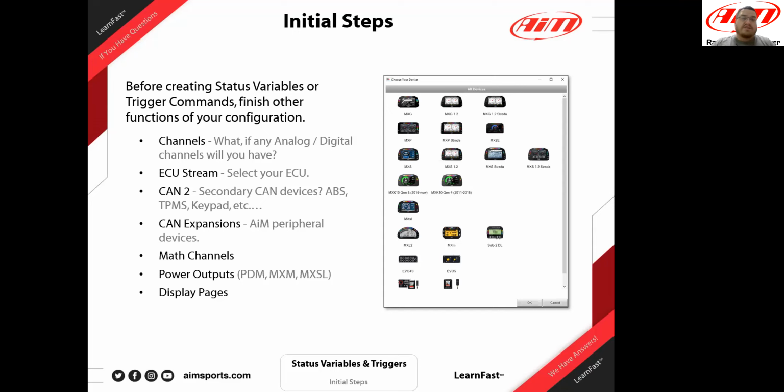So first, you'll need to set up your channels. Very simply, what are you getting for analog and digital channels? If you're plugging things up, go ahead and program them. You might grow, you might add things as you go, but consider this a starting point. ECU streams, easy enough. If you're using one, go ahead and select it. CAN 2, this one's tying in more and more. We see growing CAN 2 usage, and with the PDMs especially, you're starting to get a large amount of these things added on, and how they play in is a huge factor.